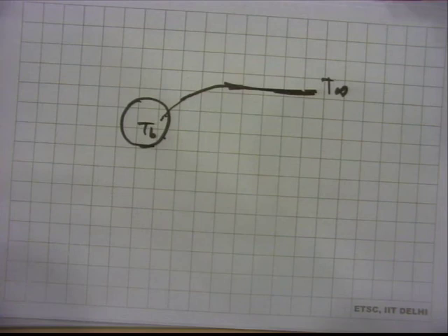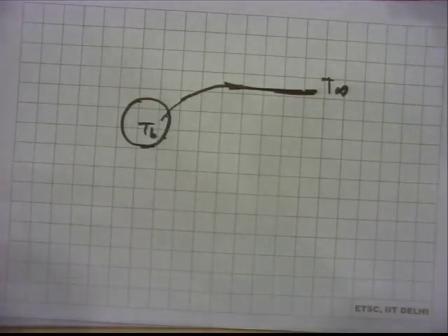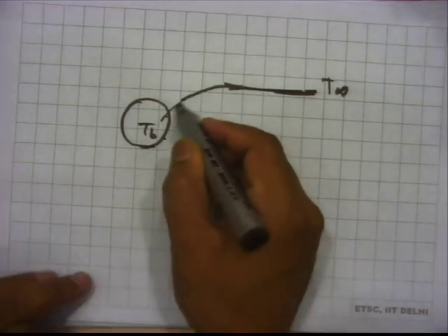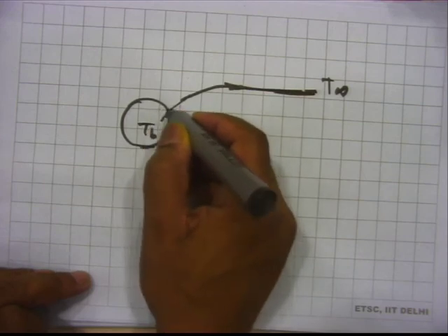Okay, so this is one way of raising the temperature. We are thinking about a situation when there is a high temperature environment and the droplet in fact reaches close to boiling point temperature. There can be other ways also, but before combustion, suppose you give a spark and then a flame is getting formed, then also it will get heated, but we will not go to that because that is closer to a combustion situation. So, there will be a temperature gradient which will help this to evaporate.